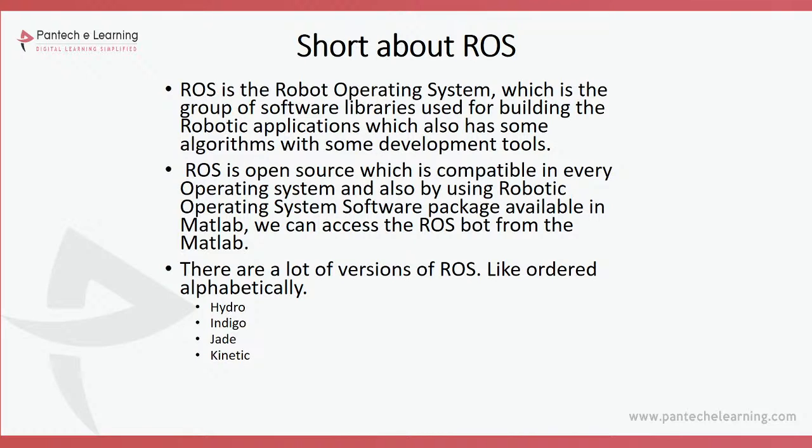In that space, now we will think about how the Raspberry Pi is able to work with this LiDAR. For that, we have to apply one important operating system known as the Robot Operating System, ROS. For ROS, we have a special Ubuntu OS. Inside that Ubuntu OS, we will be able to read all the data we are capturing from the LiDAR.